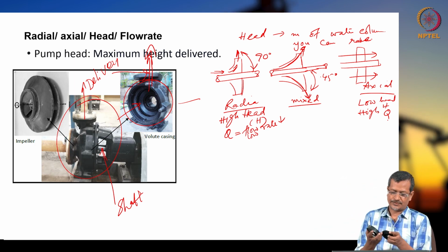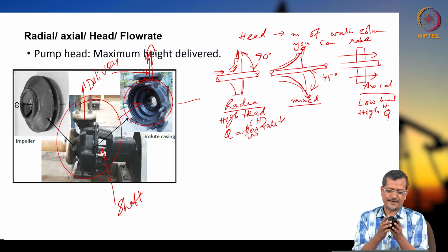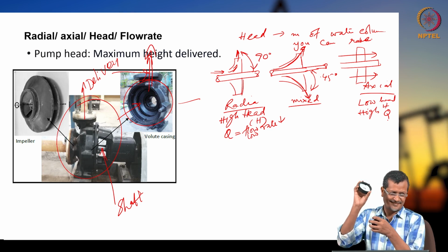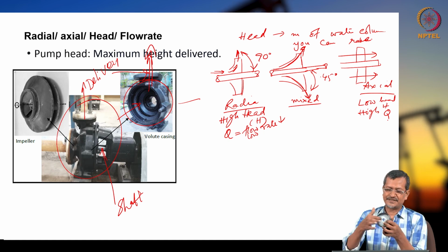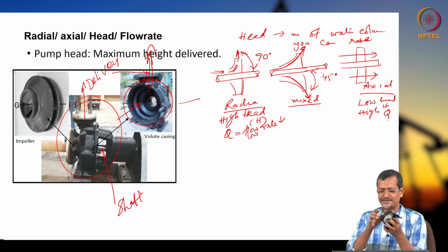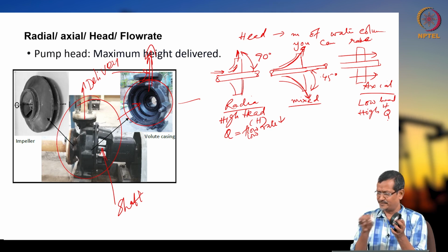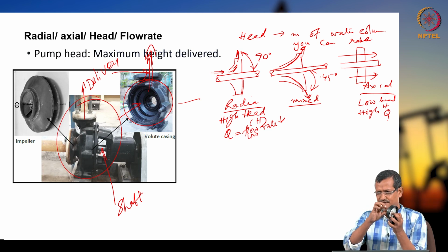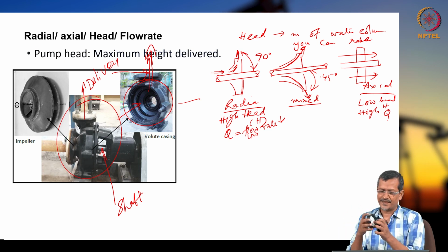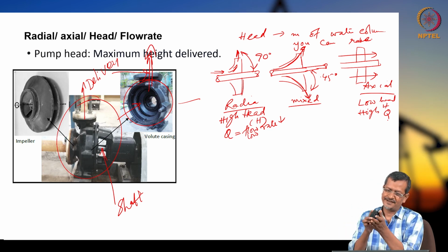Okay. So, impeller eye, fluid is entering, and this is my casing. But what is the diffuser? The diffuser is the white portion. The white portion is designed in such a way, like the opposite of the impeller, in a similar way. It will take high velocity fluid, reduce the fluid velocity, and increase the fluid head. The impeller we put inside,